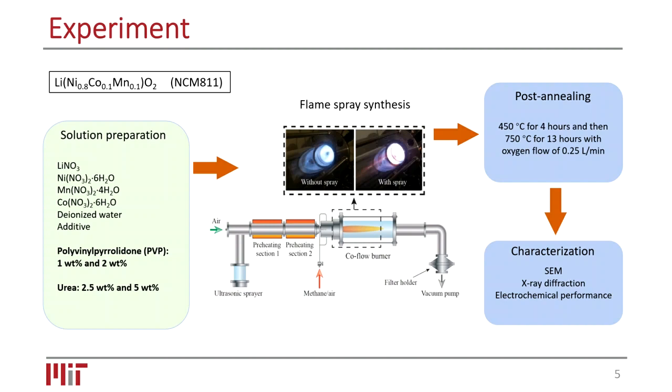After they were collected, they were post-annealed at 450 degrees for 4 hours and then 750 degrees for 13 hours in an oxygen atmosphere. At this step, we consider the material synthesized, and then it was characterized by different methods such as SEM, X-ray diffraction, and the electrochemical test.